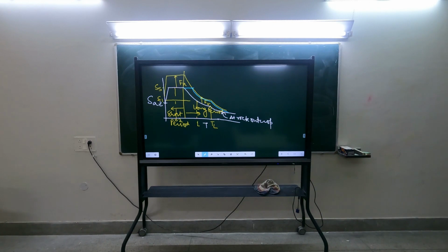So here you understand the importance of soil. Other aspects of the soil, bearing capacity and soil structure interaction, are different. The ground motion itself due to soil in zone 2 can be higher than that in zone 4 in certain types of soils, not in all types of soils. So this you have to keep in mind.